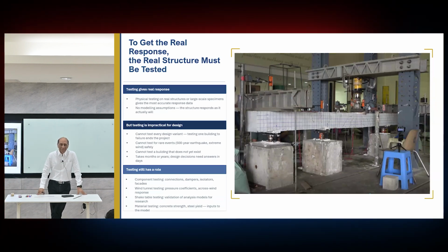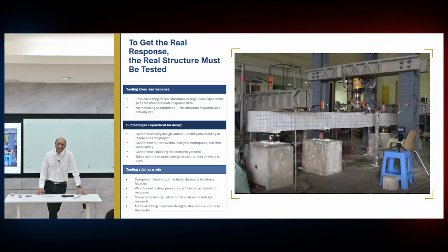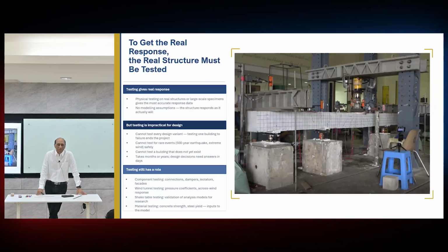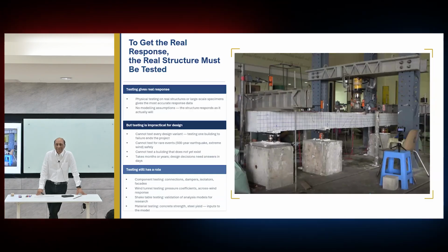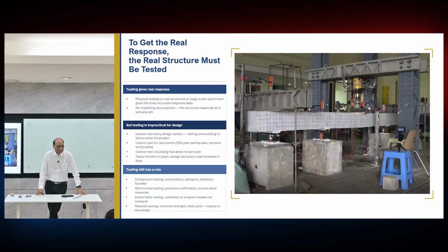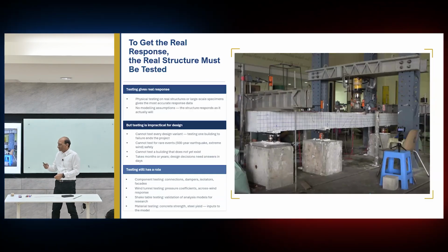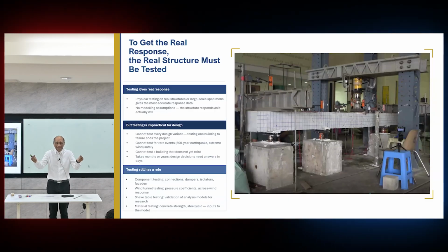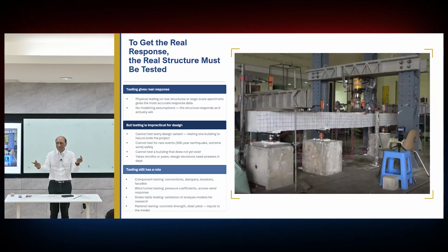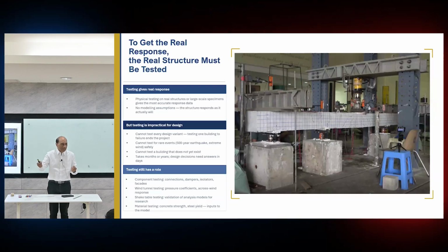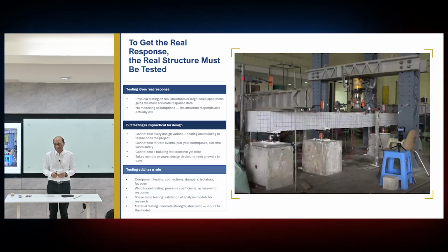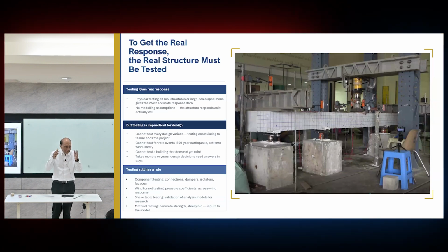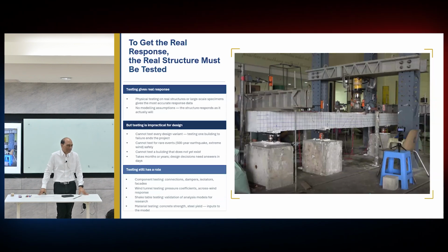In this structure also we made a mistake. The two displacements were not equal. I looked at it and I thought you guys did a good job, but actually not. So many issues still there because somehow we didn't get the perfect response as we expected. But your model always gives you nice results. Your model was saying, this is a fixed support, so I will get equal reaction here. But in reality, they were not equal because you made some inequalities there. So that means the real response varied from your model right away, even in a controlled lab environment.